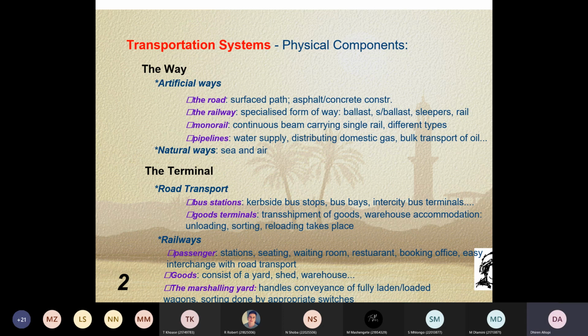And above the base layer, then you have your asphalt layer, your premix, okay, that you're referring to. And the main purpose of your asphalt layer is for skid resistance purpose, to give you a smooth path, so good riding quality. But it's the superimposed layers under it that helps in terms of reducing the stresses due to your wheel load.